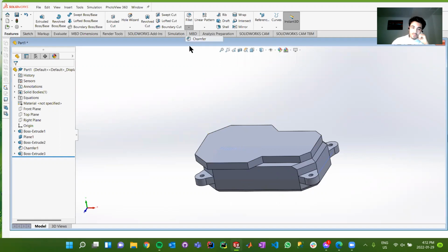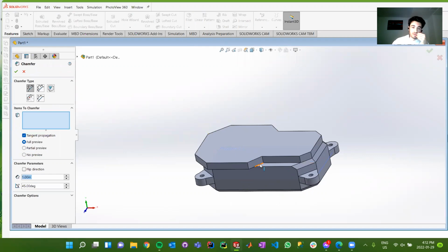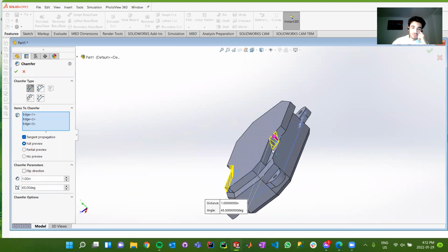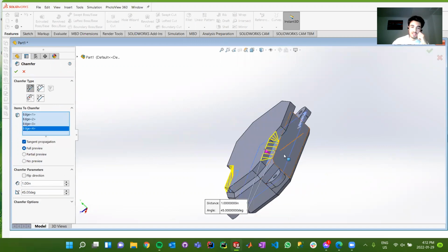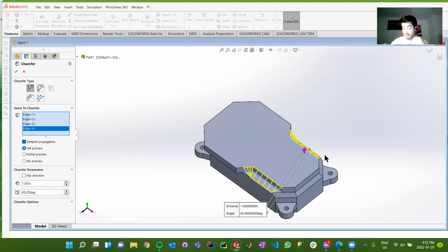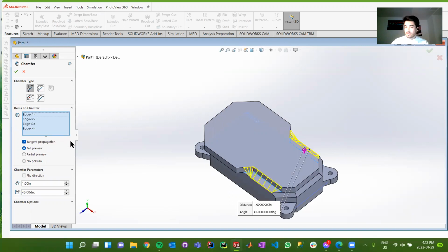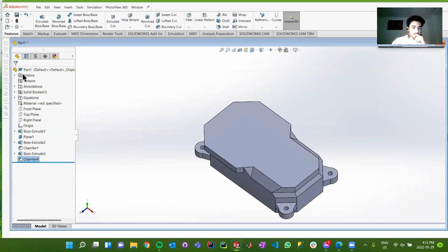So I'm going to implement some more chamfers. Notably within these inner edges, that's where we're going to approach this. So I'm going to put in some 1 inch chamfers on either edge, and I'm clicking the edges of intersections such that it blends them together and makes it one unified slope. Let's see if we can do this. No. Sometimes with the chamfer tool, you have to split up how many chamfers you do because it doesn't really recognize which parts to do quite as well until other parts have been modeled.